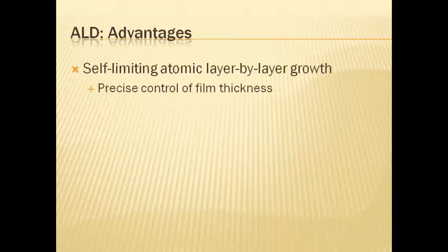As we browse through the different slides, it must have been quite evident that ALD offers a number of advantages that are inevitable to be exploited in today's fabrication technology. At different points in the presentation so far, we have mentioned those advantages, but it's certainly prudent to have a summarized look at them. The first and main advantage is the self-limiting nature of the deposition. As explained using relevant graphics, as the atomic or molecular layer becomes saturated at each pulse stage, a highly controlled layer-by-layer growth can be maintained, leading to precise control over the film thickness.